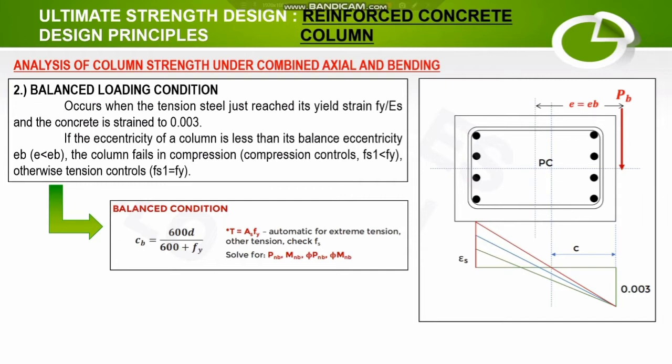Then, we are obliged to solve for the nominal balance load, nominal balance moment, the ultimate balance axial capacity, and the phi Mnb.